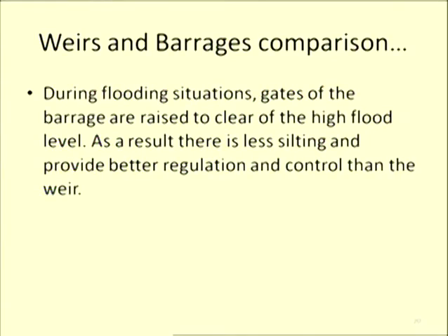So that is the benefit: we can regulate the silting in the barrage, but silting in weirs is difficult. We need mechanical devices to eject the deposited silt upstream.